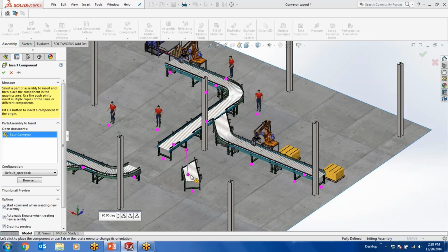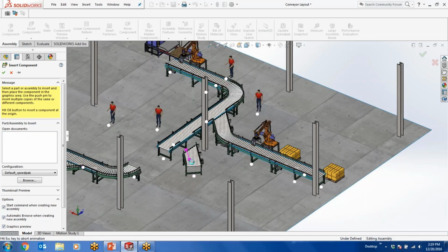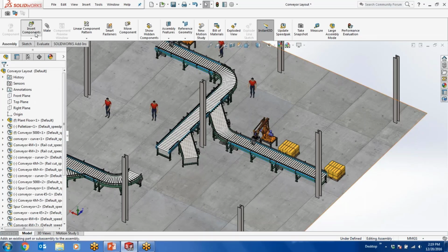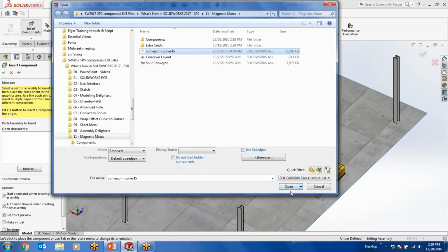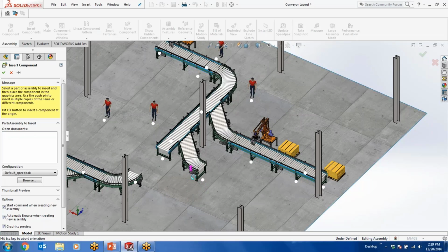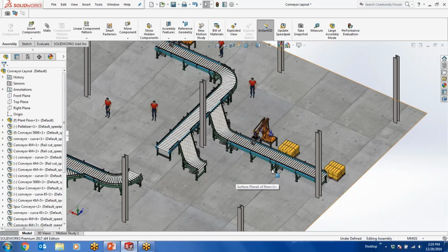But what you can do is set these sub-assemblies up such that when you insert them, they automatically snap to these predefined points on other sub-assemblies. So it's just a click and play type deal right here, where you can bring in those components. We'll bring in a second one here, and you can just snap, or if they're not quite in the right configuration, you can just hit the tab key and then it orients them 90 degrees with respect to where they were. And it's very easy to move those around.